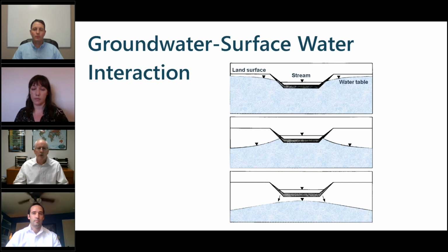Now, groundwater surface water interaction in GAMs has typically been incorporated using standard MODFLOW packages. John mentioned a couple: the river, stream, drain, reservoir, among others. These are head-dependent boundary conditions shown here. The water level in the cell is calculated and compared to the water level that's specified in the surface water boundary condition. And depending on which head is greater than the other, the water either moves out of the stream and into the groundwater budget, or out of the groundwater budget and into the stream.